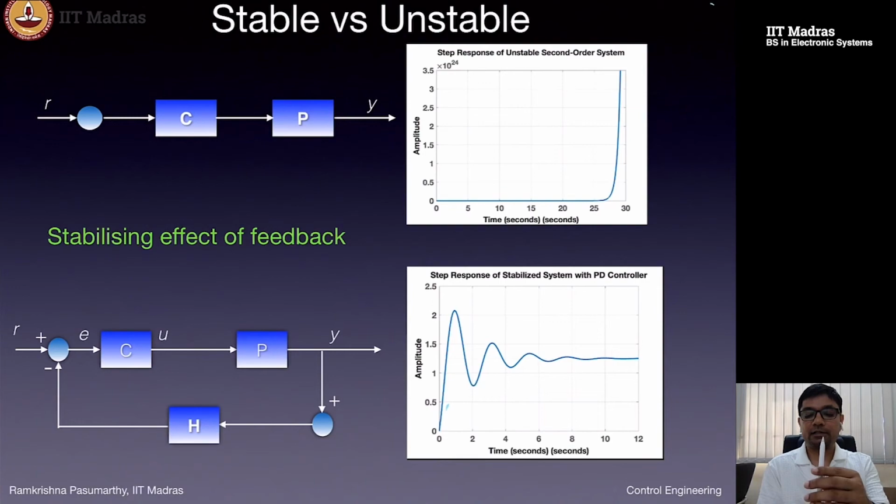What happens in an open loop situation, if I start from here with a little perturbation, is that the pendulum just falls off. This situation where it just falls off is what we will call unstable behavior, where the output goes unbounded mathematically, and the system moves away from the position that we want. Like in the pendulum, I just want it to be in the downward position, and in the inverted pendulum, I want it to be stable like this.